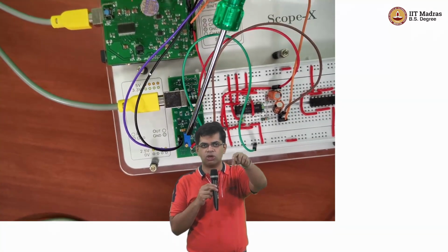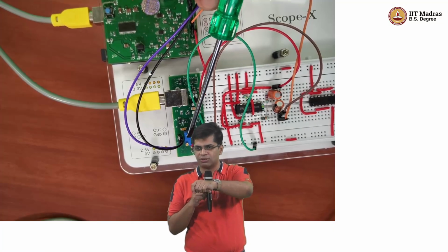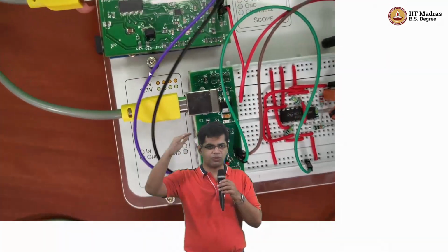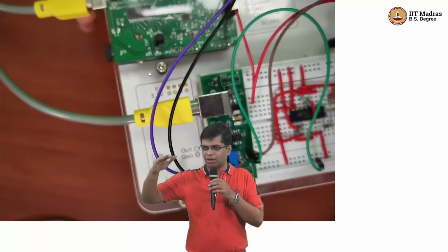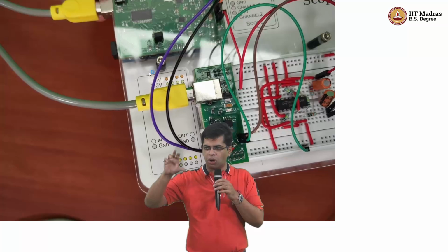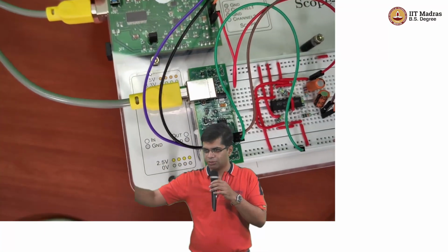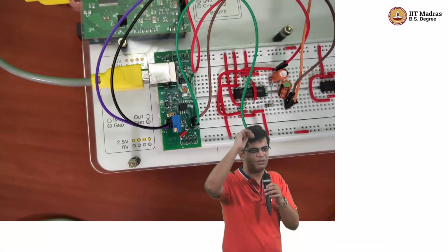And there's a small potentiometer there, and all of you have a screwdriver. Essentially what it does is it takes this voltage, which is a 0 to 5 volt sine wave, and when you use the pot, it will change the amplitude, but it will still ride on 2.5. So for all practical purposes, 2.5 is like your 0.